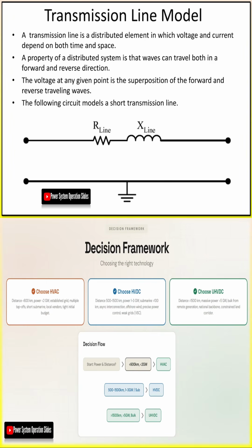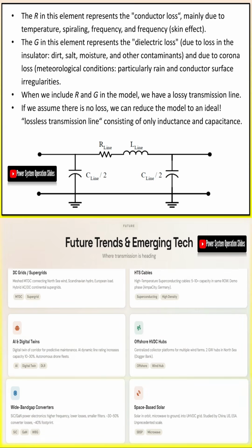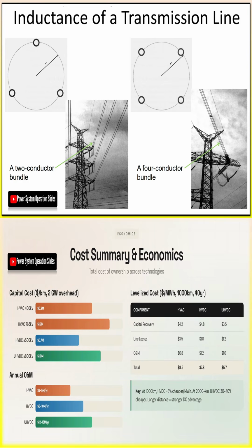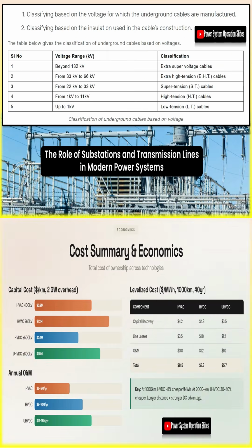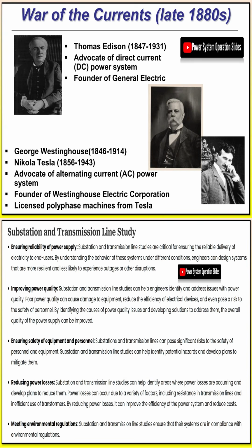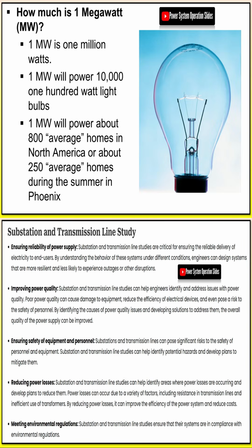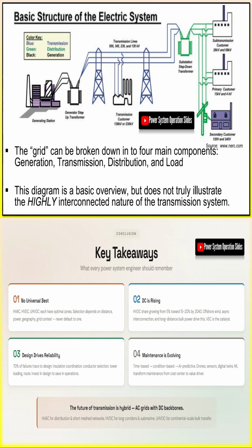High-voltage alternating current transmission has dominated the global power landscape for over a century, leveraging the simplicity of transformers for voltage step-up and step-down, the robustness of induction motors, and a well-established ecosystem of standards, protection systems, and manufacturing expertise. Typical HVAC systems operate as three-phase networks at 50 or 60 Hz, with voltage levels progressing from 66 kV through 132 kV, 220 kV, 400 kV, and 765 kV, with the highest operational voltage reaching 1200 kV in China.